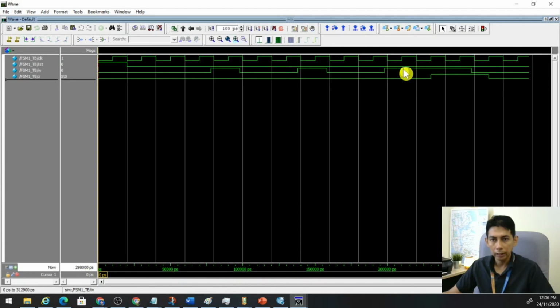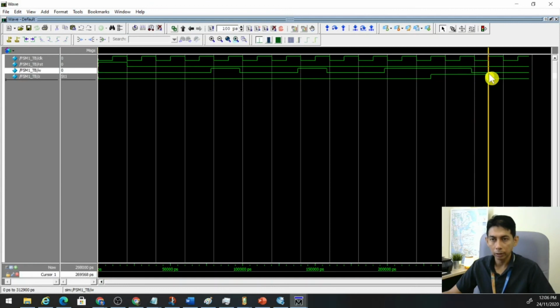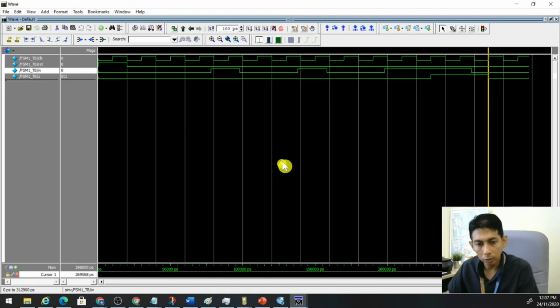But here we see that for two consecutive measurements, the first one and the second one, the speed is still exceeding the limit. So now Z is equal to 1 already, and the third measurement is still 1. So if W stays 1 until it goes down to 0, then Z goes down to 0 here, right? So this is how the FSM is designed and simulated in Quartus.